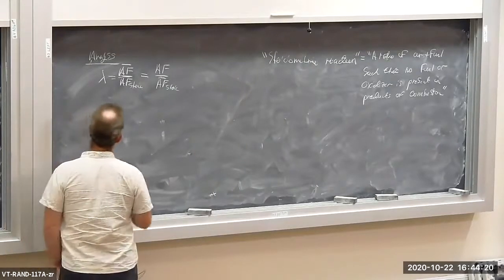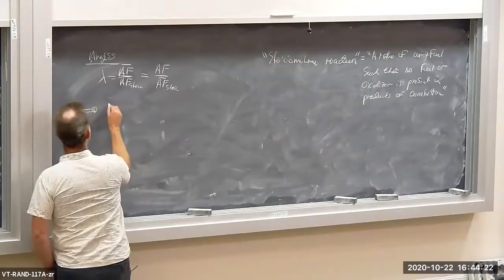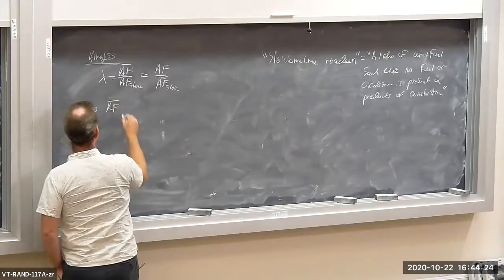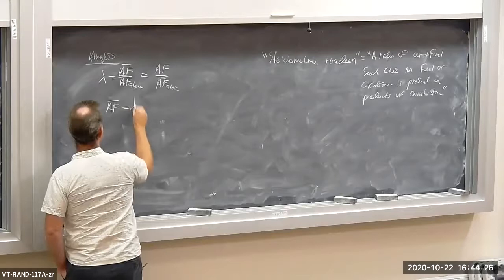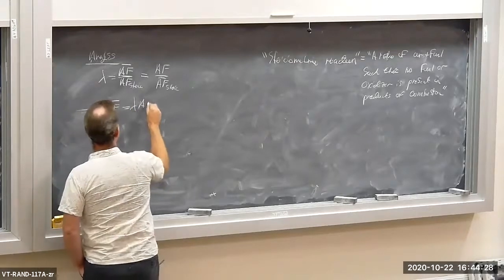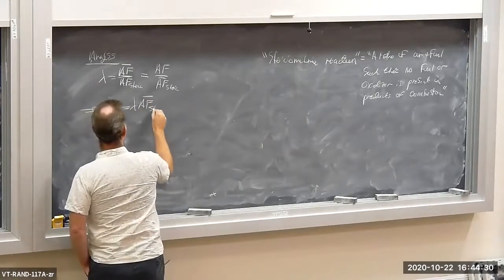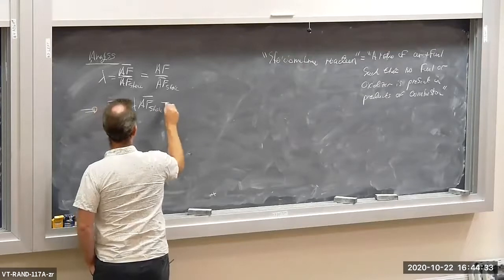So that means the air-fuel ratio on a per mole basis is lambda times the air-fuel ratio for the stoichiometric reaction.